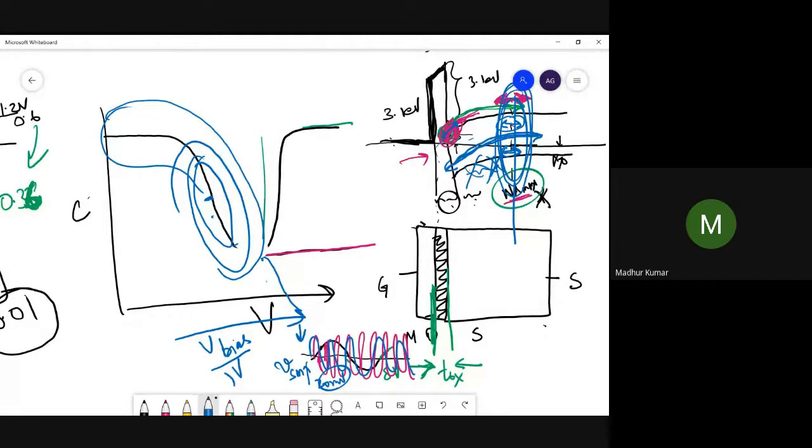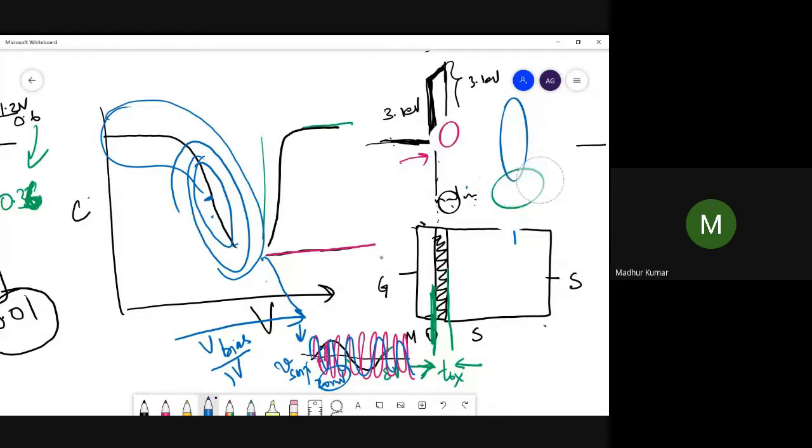But we have also given a gradient. We have already given a gradient to EC and EV. That is an inbuilt gradient. In a static condition, suppose you are not applying this AC signal, what would happen? Would there be any flow of electrons here? No, sir. In the DC condition, there is no flow of electrons.